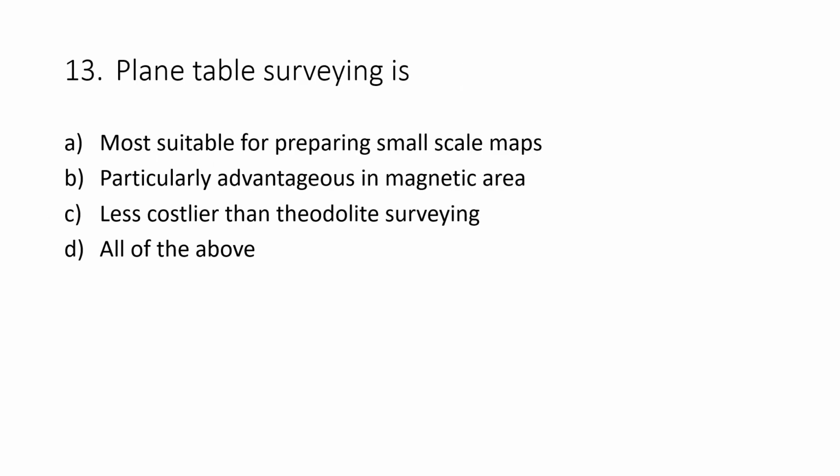13th question. Plane table surveying is most suitable for preparing small scale maps, particularly advantageous in magnetic area, less costlier than theodolite surveying, all of the above. These all are regarding plane table surveying, so the answer is all of the above.